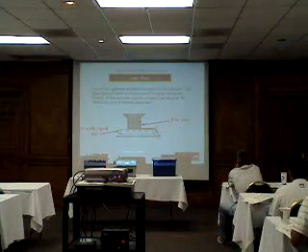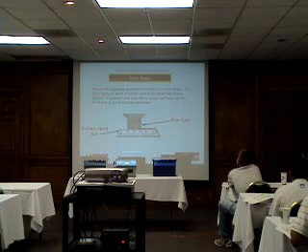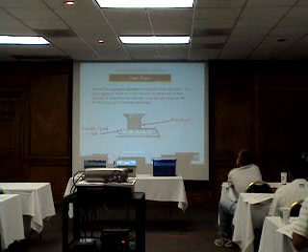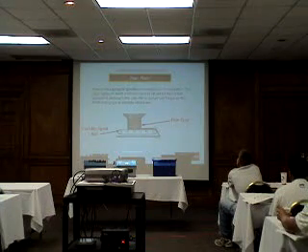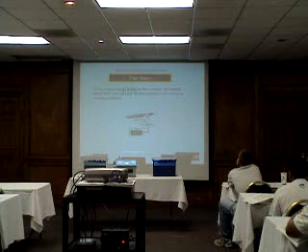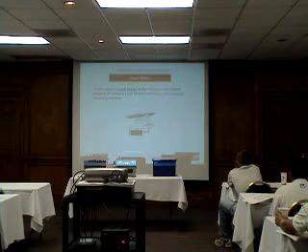Gate, control how much material you have coming out, or you can just set that at a set height, and then the variable speed, you can adjust the RPMs of that belt to adjust the flow of aggregate going to the mix.